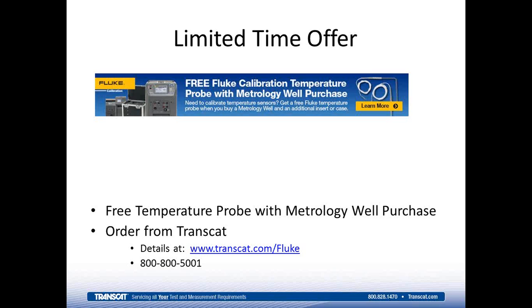This one: is the proportional band a reference to proportional parts? Well, I'm not sure I understand that question, but I'll try to answer it the best I can. A proportional band is designed to dictate the behavior of the controller in a dry well on how it behaves if the temperature starts to drift a little. So if it starts to cool off or heat up, the controller wants to take over and adjust for that. The proportional band setting will determine how the dry well behaves when it reacts to that. So more like a response, if you will, from the dry well is what the proportional band is.